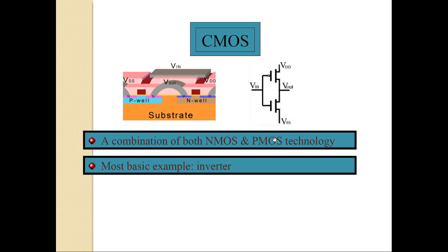So I will repeat this concept for you guys. This is my PMOS. How to remember? The bubble is there. For NMOS, the bubble is not there. For PMOS, if I am applying 0, then this will turn on. The gate acts as a push switch. For 0, it will push and VDD is connected to the output.